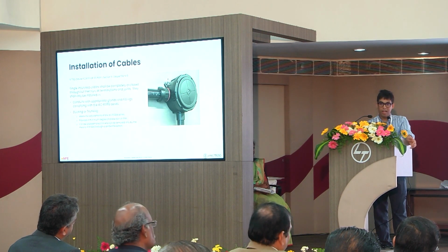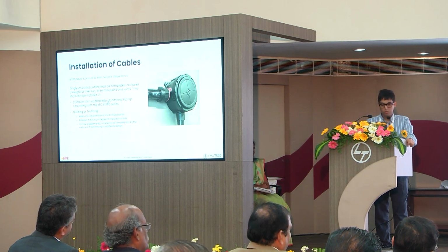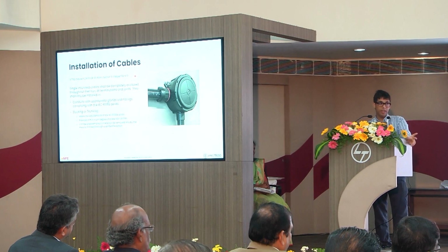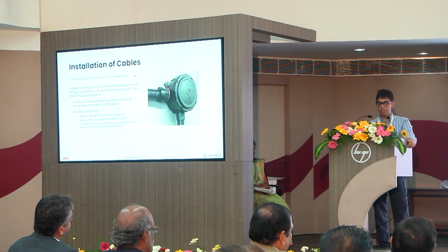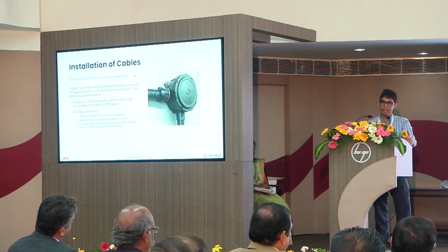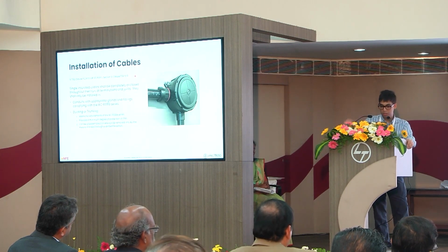So you need to have proper glands and fittings here for your conduit, and this is an IP rated enclosure. That way you're maintaining the IP rating. And these will obviously conform with the 61386 series. Now, if you have trunking or ducting, like we mentioned, 61084 is the IEC standard. And it's very important that if you're using single insulated cables, they need to meet a minimum degree of protection of IP4X. So an IP33 ducting cannot be used with single insulated cables because that doesn't contribute to the first 2 layers. It's not basic plus fault protection.